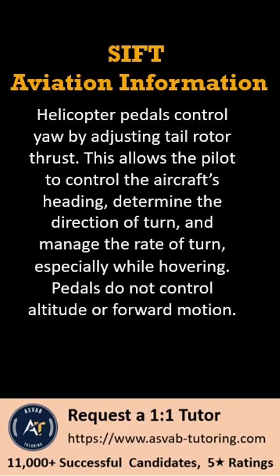Helicopter pedals control yaw by adjusting tail rotor thrust. This allows the pilot to control the aircraft's heading, determine the direction of turn, and manage the rate of turn, especially while hovering. Pedals do not control altitude or forward motion.